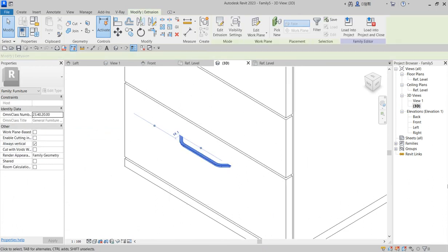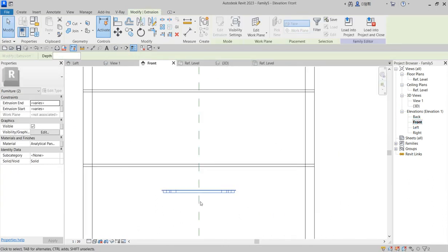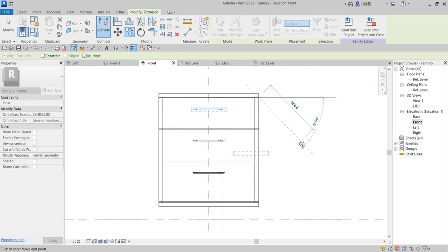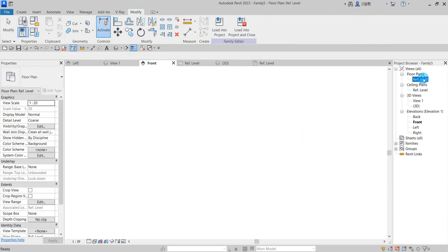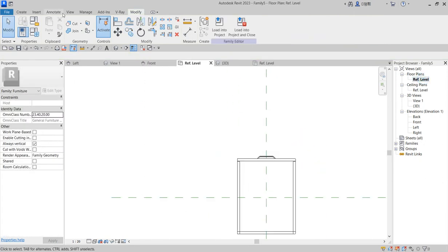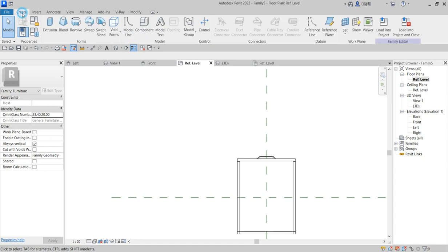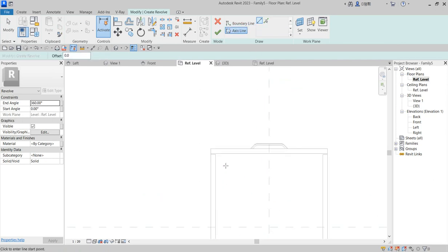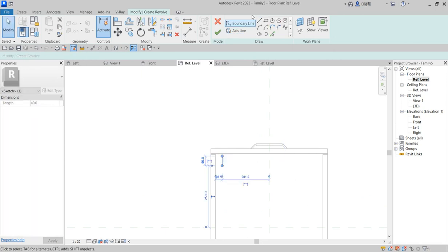That is what you do, and you select this and go to your front elevation. From front elevation you select and paste from here to this and to the last. Good. As you have done, you need to do a quick check. So how do you do the stand? You do the leg by using not extrusion this time, but I want to use revolve. So I'm clicking on revolve, I'm using it in this way. I'm going to use axis, click on axis. Axis line, draw it that way, 40.